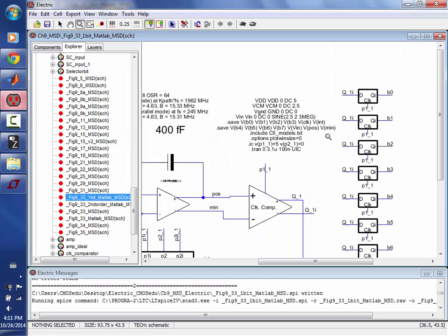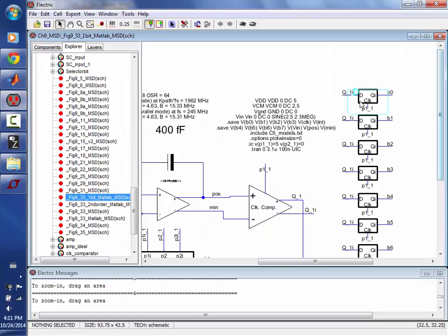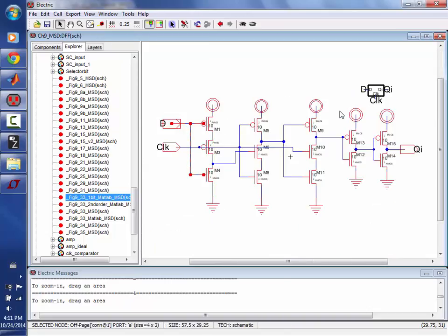So I went over and looked at the corresponding schematic here, and what's used is the following. It's this circuit right here, and it's a dynamic circuit with 2 inverters. I put those just so I'd have really good logic levels. So what I want to do is make this using LT-Spice, make a symbol, and then put it in the sim.